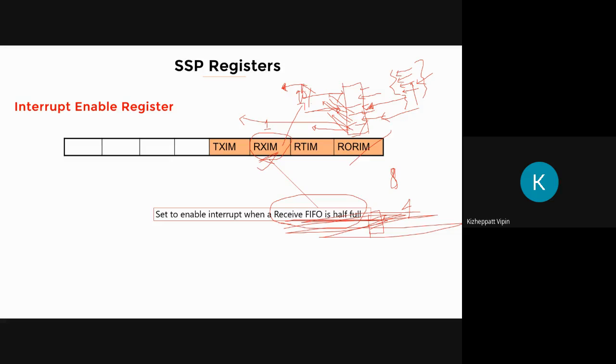You are using Vivado there, right? Are you using Vivado? Yes, sir. Have you used any IPs in Vivado? IP-based design. So we are going to use it now. Like we haven't. When you use it, there are FIFOs. Choose FIFO hardware implementation, and you will see the options. So your normal empty, full, everything will be there. Then you will have an option like programmable full and programmable empty. I'm saying like in Xilinx Vivado.